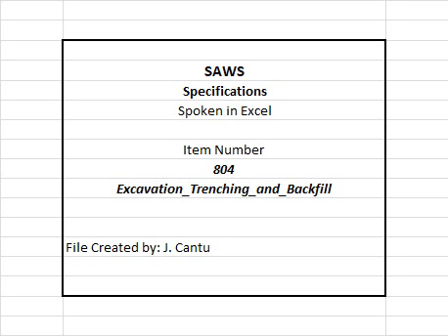D. For diameters larger than 24 inches, initial backfill material shall be evenly and simultaneously spread alongside, under the lower quadrant of the pipe and over the pipe in 18-inch first lift, or 12-inch lifts to a point sufficient to a minimum of 1 foot above the top of the pipe, see Drawing Series DD804. Placement of the first lift of initial backfill shall be subject to inspection and approval prior to placement of second lift, which shall extend from the spring line of the pipe to a minimum of 1 foot above the top